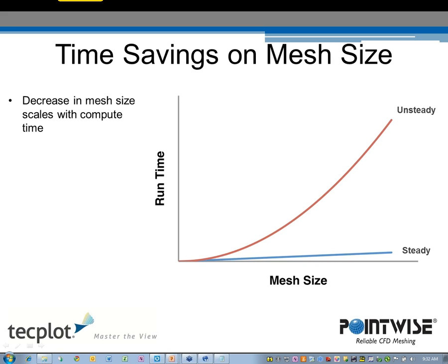Robert Gordon had a question. Would he be able to have access to your script? He'd also like to learn how you could use this optimization perhaps even with OpenFOAM rather than with Fluent. Okay, yeah, I'll get this one. Sure. The script will be available. Like Chris mentioned, it can be run in batch. You can strip the GUI out and run it in batch mode from the command line. Right now the script doesn't export to any solver, but Pointwise does export to OpenFOAM, so you can take this script and actually use it with OpenFOAM as well.